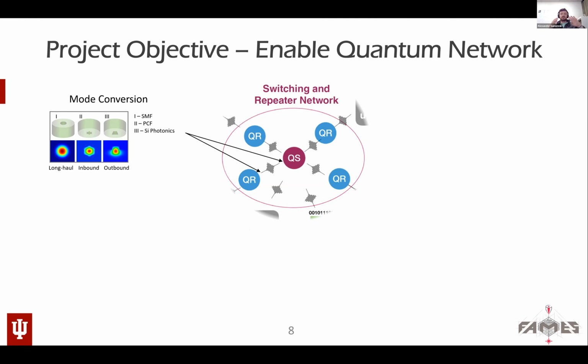If you just brute force try to couple a circular mode, it's like trying to fit a square peg into a round hole; not all of the peg will make it into the hole, right? So you need to reshape adiabatically the peg into the shape of the hole that you are trying to fit it in. So it fits.